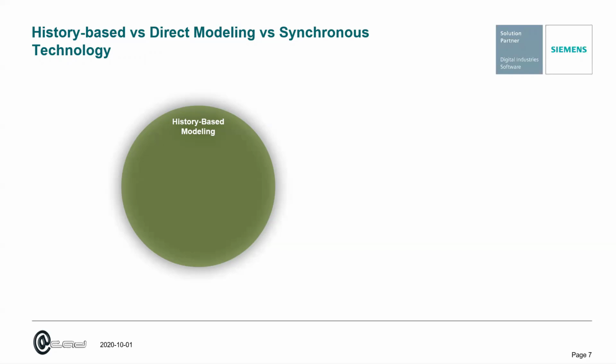So the benefit of this approach is that it is dimension driven, where we can actually change the geometry by editing the dimensions in the sketches. It is also highly automated. For example, when we edit the dimension of a feature, most of the time it will automatically change the dimension of other features as well, based on how we create the relationship between all these features. It is also feature-based because there is intelligence built into the features. For example, a hole is not simply just a hole. It can contain information like whether it's a counterbore or countersunk hole, whether there is any thread applied to the hole, and things like that.